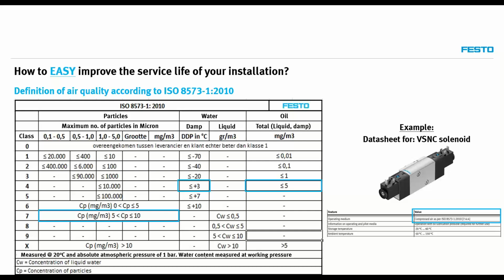And of course, Festo has suitability for our products and our life cycle for this middle section, which is a very forgiving and very robust installation. The higher the equipment and the more requirements you ask of the pneumatic components, the more expensive it's going to be, because you will add more stages of filtration and more resistance, and that needs to be overcome with typically more energy.